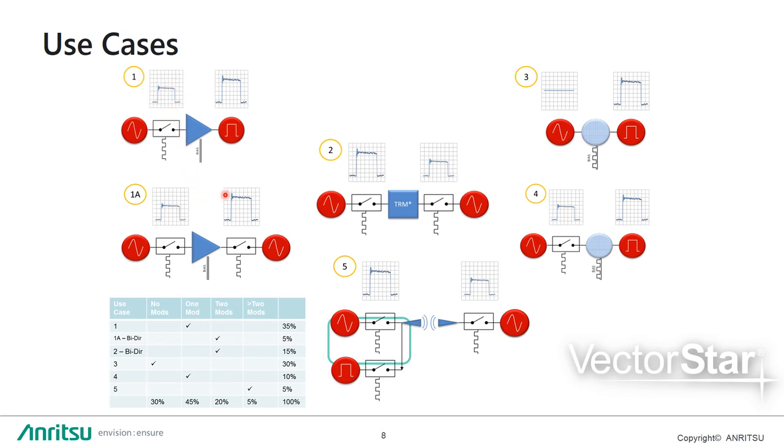In scenarios 1A and 2, a radar system component test is using a 2-modulator test set. The user may either be testing a component in which the normal use is with a unidirectional pulse, but the user wants to include the response to a reverse direction pulse for a complete component characterization, or in 2, a TR module in which bidirectional RF pulsing is required.